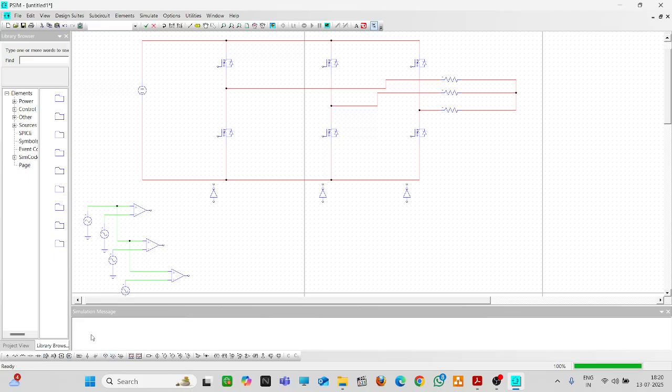So now the on-off switch controller. This is very much required. We will be placing this. Very essential because there is a difference between the control circuit and the power circuit. You need to isolate the control and the power circuit. You cannot directly connect the control circuit and the power circuit. What will happen? The current will flow from the power to control and control will get damaged. So to provide the protection, this has to be done.